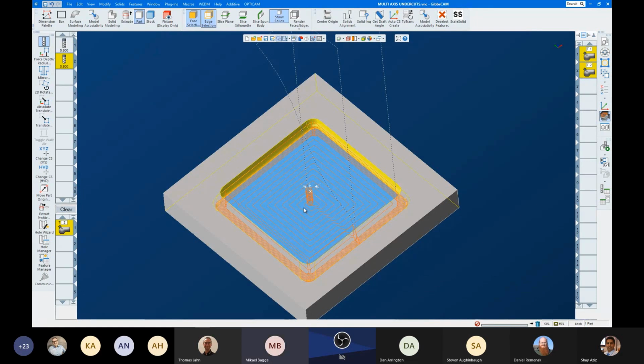Dan, you mentioned in the beginning, I have used this probably once or twice. Once in a project where the part was pretty big, like 250 millimeters, and the tool was like 2 millimeters, very small. The toolpath this one creates for an Integrex machine with rotary Z-axis and B-axis is absolutely fabulous. The only toolpath that I found in Gibbs that I could use for cutting titanium. So that was all hunky-dory.